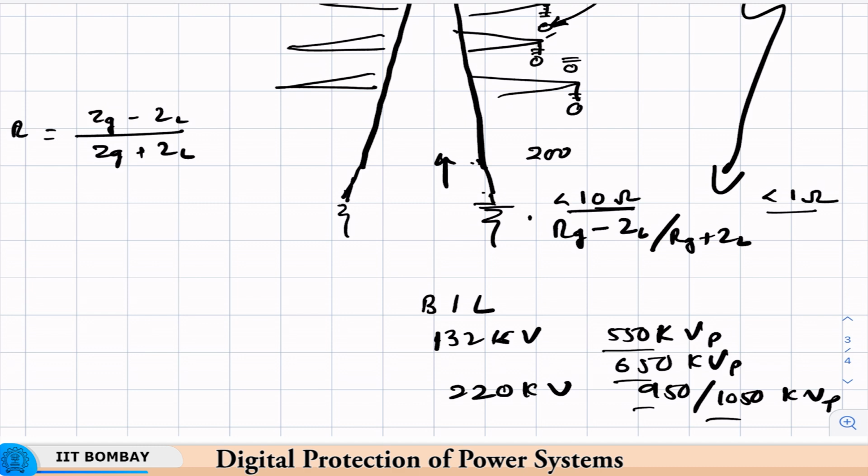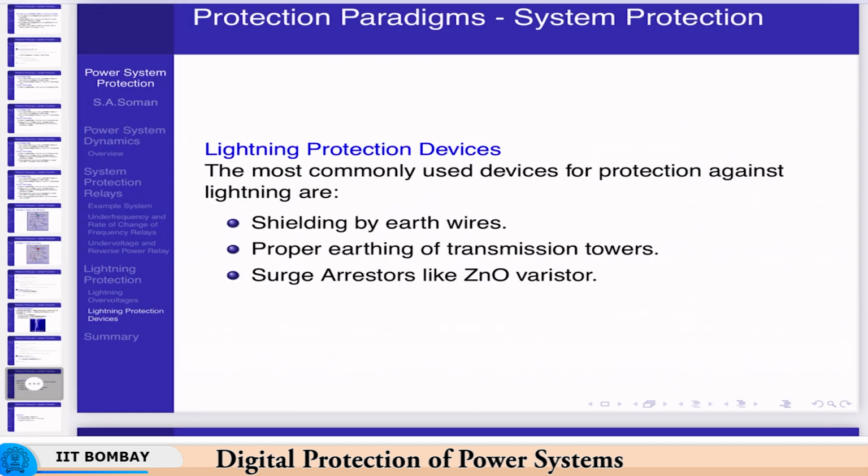Okay. So to prevent that from happening, we use equipment like surge arresters. These are ZnO discs which are stacked depending on the voltage and the current ratings. They could be stacked in series and parallel, and this is such that at normal voltages they will not conduct, so they are sealed off, and when a lightning stroke occurs due to the high voltage, the surge arrester will conduct and divert the lightning stroke, thus preventing it from reaching the substation equipment.